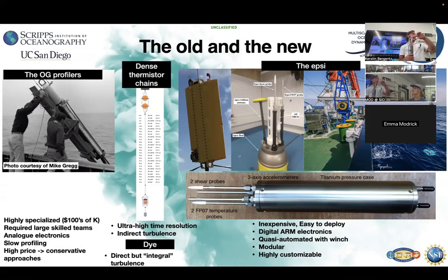Very simple principle, right? So these are just two megahertz transducers, and they're just pinging back and forth at each other. And if the sound takes longer to go one direction than the other, then there's a flow in that direction. And so we measure this to a time precision of 20 picoseconds, 20 times 10 to the minus 12. And that allows us to get these incredibly precise and low power velocity measurements.